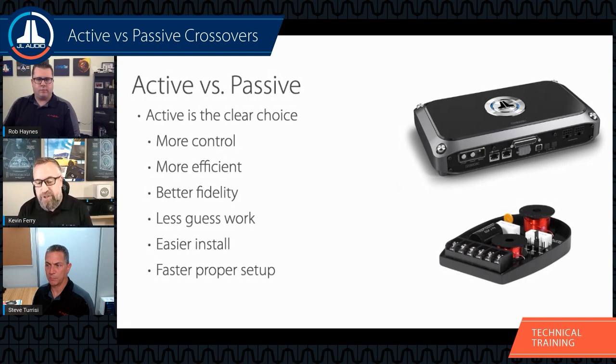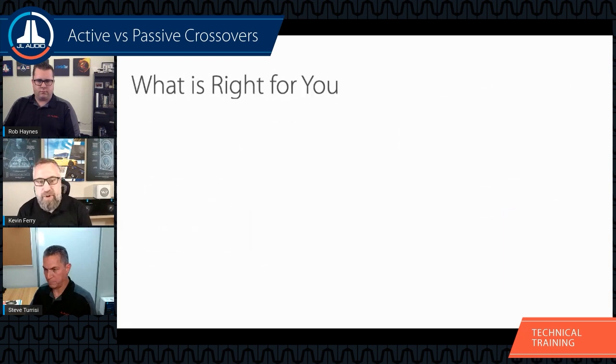Being able to make a level adjustment in DSP is a lot easier than finding where this is underneath the carpet or inside the door and pulling the jumper and doing all of that stuff. So it is a much faster setup time when you are doing that properly.